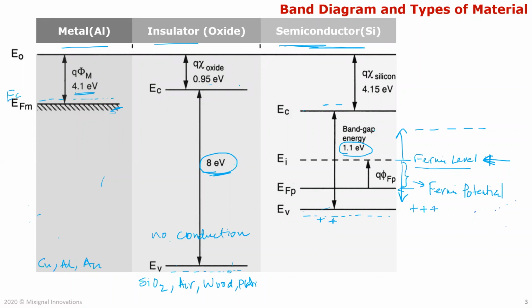So for example, if you dope a semiconductor with something where there are a lot of electrons, where the Fermi level is now very close to the conduction band, you need very little energy to move to the conduction band, which means that the number of electrons available for conduction goes up at room temperature compared to an intrinsic level. In a semiconductor, the entire band gap is roughly 1 electron volt, which means this is half an electron volt, which is actually a lot as a Fermi level. But let's say you dope it such that now it's only 0.1 electron volt. Now, even at room temperature,